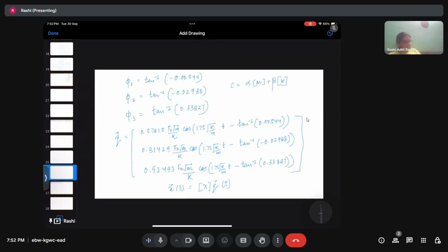This is a proportional damping, right? This is the proportional damping. But for the solution that I've given over here, it is because of the proportional damping. We have already considered that the damping is of this form, okay, where alpha and beta are constants. But if the damping is not proportional, then what are we going to do?